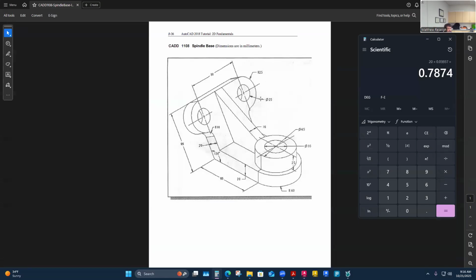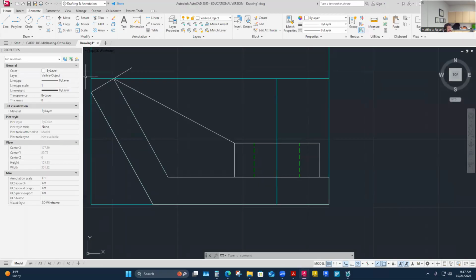So let's see. They just come down. They are concentric holes to this radius. So I've got a 25 diameter hole through a radius that's 25. And they're concentric. How far down are they? Well, I do have a linear dimension there. They're definitely 90. That's going to help me in the top view. They're just on center, so they'd be 25 millimeters down using the radius. So this is a 50 diameter across. I'll just come down 25 and then base my whole pattern off that.